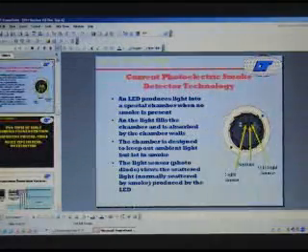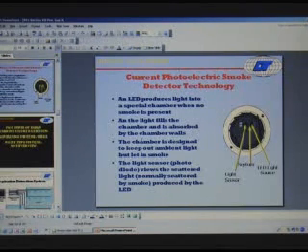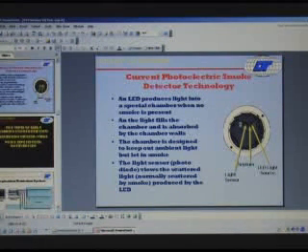The photoelectric smoke detector works this way: an LED produces light in a special chamber where no smoke is present, and the light fills the chamber and is absorbed by the chamber walls. The chamber is designed to keep out ambient light, but when smoke is present, the light scatters onto a sensor, the photodiode. You can read that.